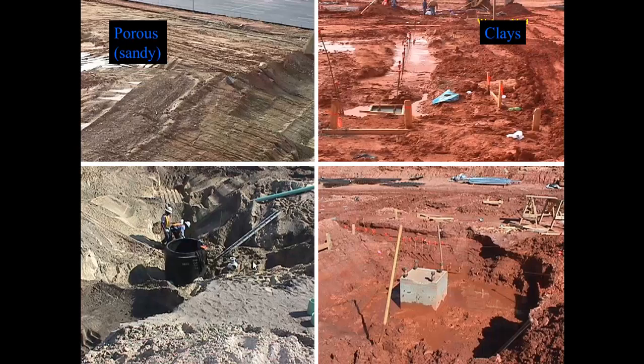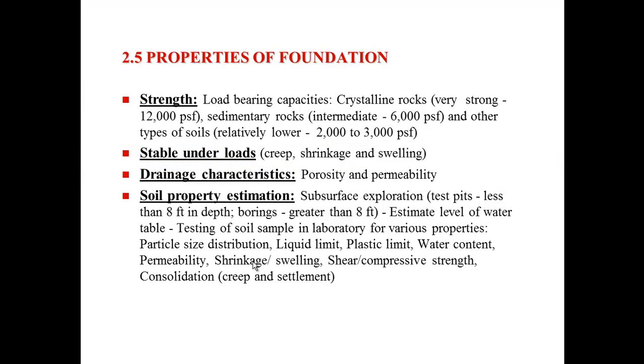So the angle of repose that we need to maintain is, oops, where am I going here? There we go. Properties of the foundation: we have the strength, the load-bearing capacity, the difference between the crystalline rock, 12,000 pounds per square foot, as opposed to different types of soils, 2,000 to 3,000 pounds per square foot.